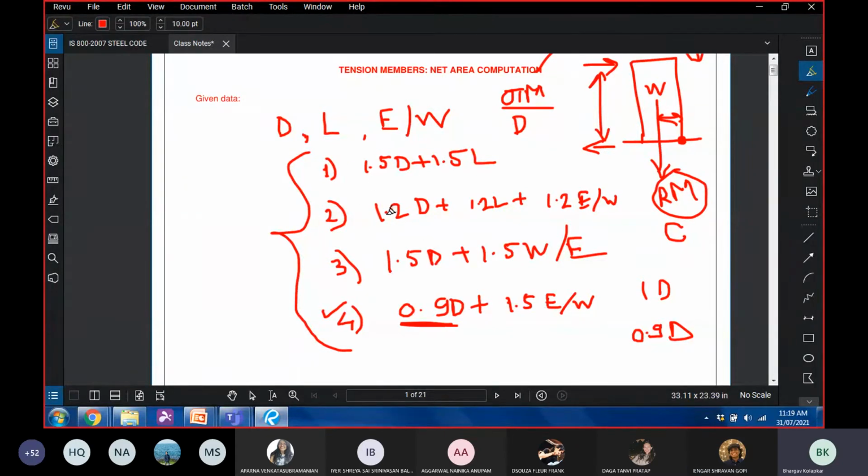So we use all these load combinations, and then we compute what, after these load combinations, is the maximum moment that I'm going to get in a particular beam, or what is the maximum actual force that I'm going to get in a particular column, and then we decide that column, beam, or slab accordingly.